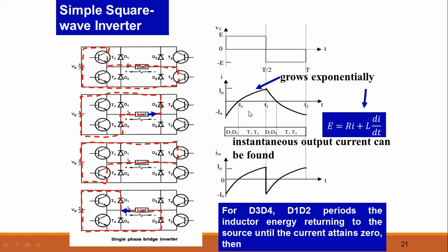So what we have to do now is a sensitive case. The sensitive case is that the circuit doesn't know when this zero crossing will occur. If we are observing over here, this negative current is flowing through the diodes D1 and D2. But as it crosses zero, this current flows through the thyristors T1 and T2 up to here.